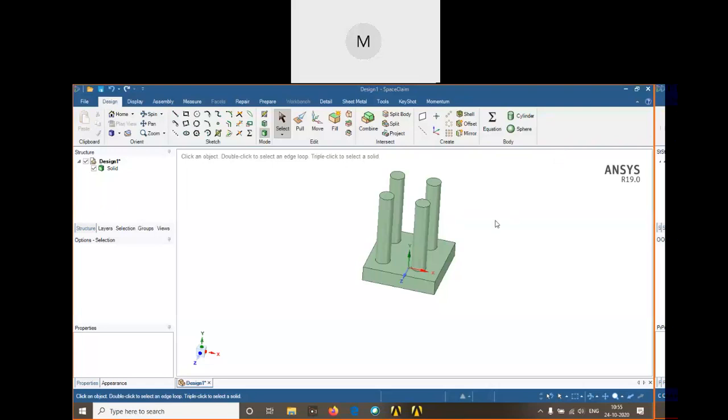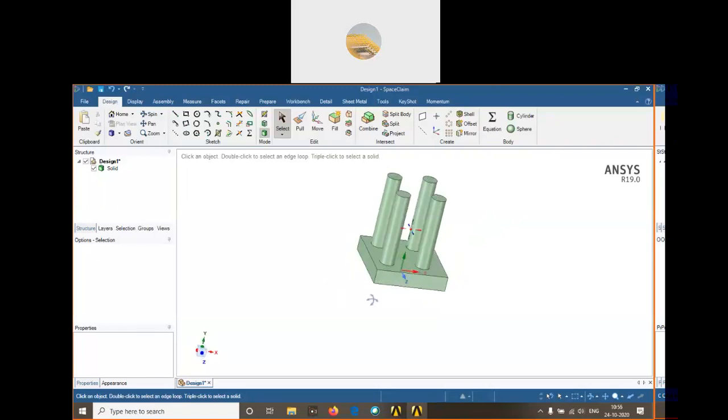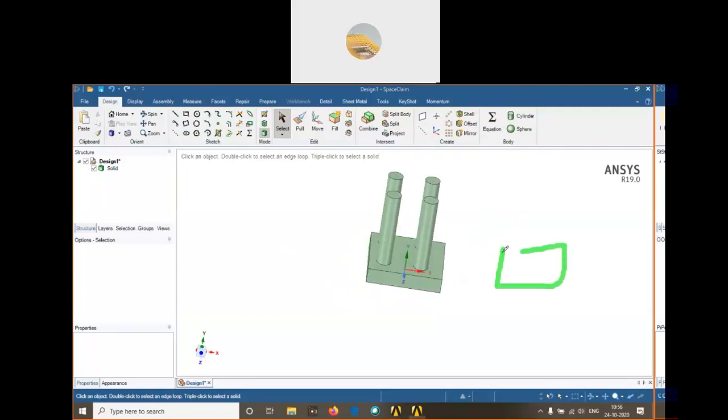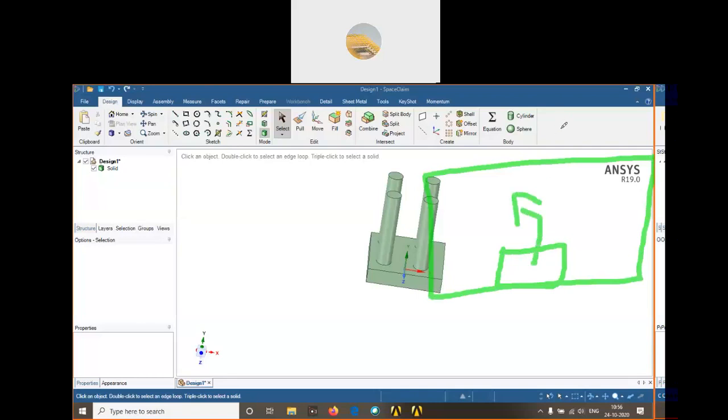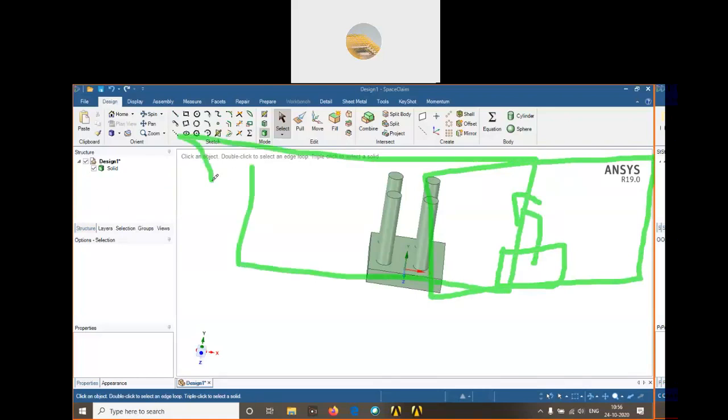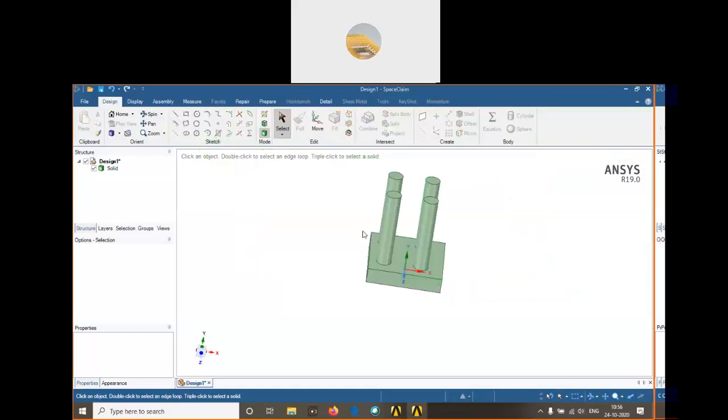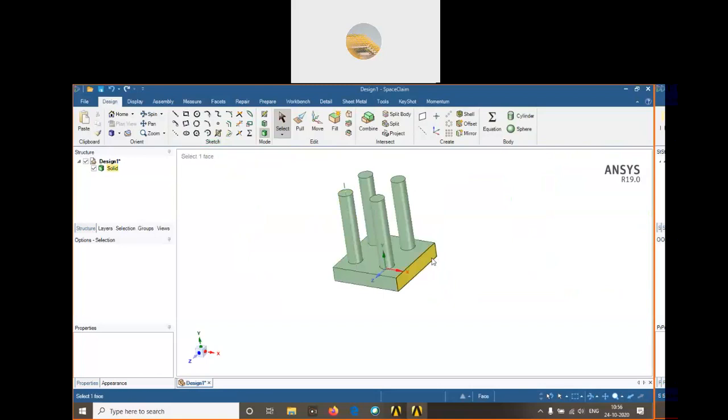Okay, so now I have my solid part. Next thing which I need is the fluid part, because guys, listen very carefully. We have a solid here, and practically we will have a fluid domain there. For example, your room: heat will get transferred from here to the room, but software cannot automatically assume all these things. So you are supposed to model a fluid domain. So let me do that.